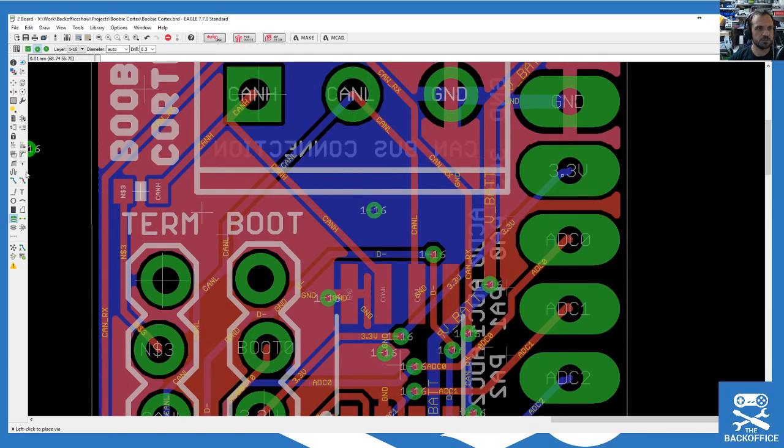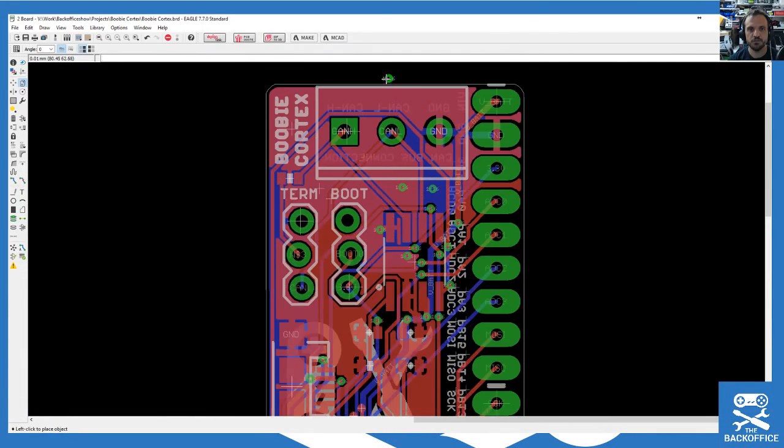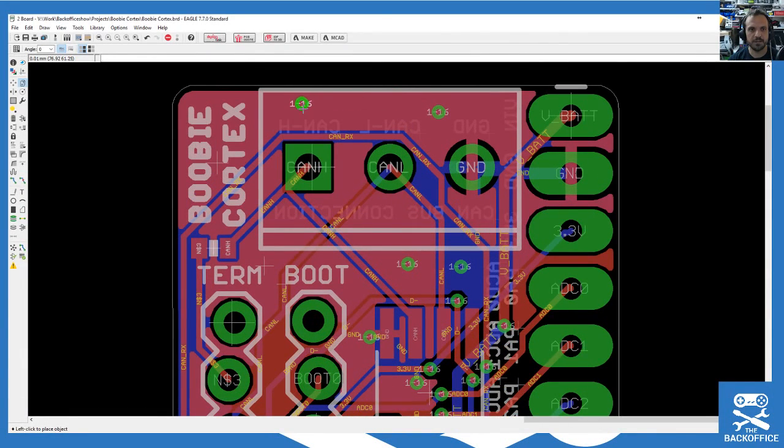So what you've got to do is put down your via and connect it to ground. If you literally just put in ground, bang, you see how it's connected up the two ground planes. So then it's really nice, because after you've done that, you can use the clone, which I believe is that. They've changed the icons in the version of Eagle since I last used it. And you can just dot them around. And actually, if you're doing it, join your ground planes all over the place.